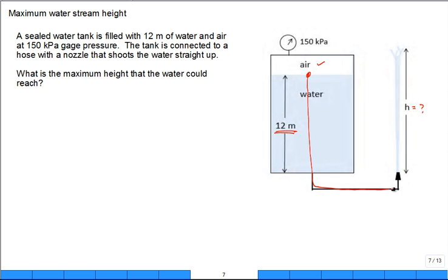And this is a case where this water jet is staying together and going up. It's against the gravity, and you get all the way up there to end the streamline. And in that streamline, you're going to assume still the lack of frictional effects and constant density. The air is not breaking it all up, which is going to happen. So we're going to predict a maximum height that, if you went out and tried to do this in the real air, wouldn't be achievable.